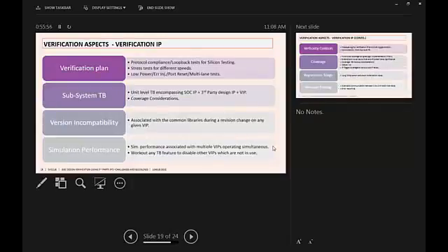So this is something, a verification aspect, which we need to have in our test plan when we are using a verification IP. Why I'm talking about protocol compliance and loopback test is that we need to make sure the VIP works, because this is going to be the first test to face at the silicon level. If they face some issues, they come back to us, so have a plan in place for protocol compliance or loopback.